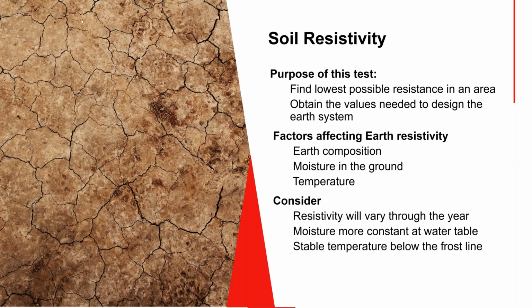And in a more practical sense, used far more often because most people don't have a lot of room to work in, you can also get values of the soil resistivity, which are critical in designing a ground system. And we'll talk about that a little bit. And be aware that resistivity is referred to in the literature as a constant because that's general terminology. But it really isn't very constant in the practical sense.